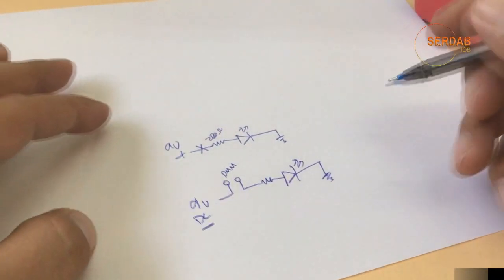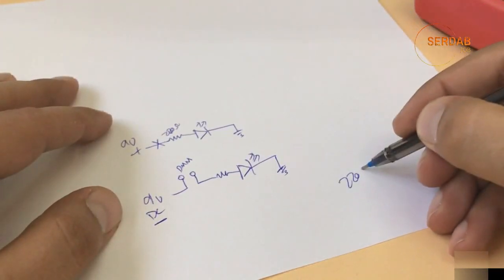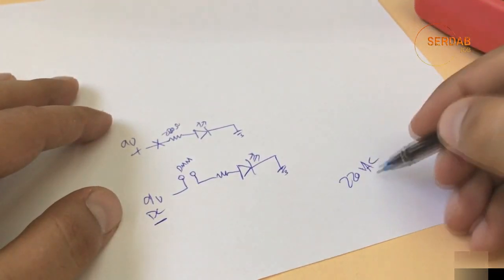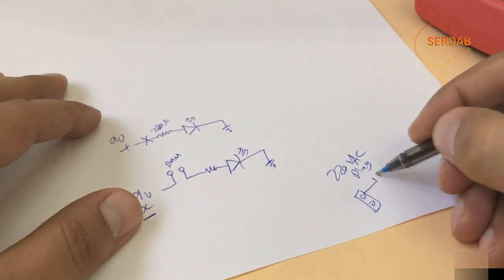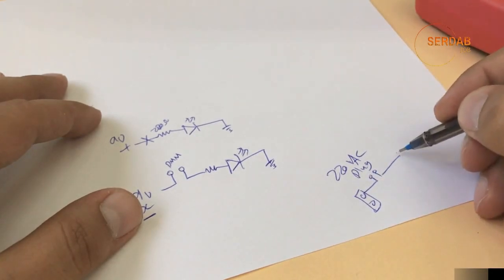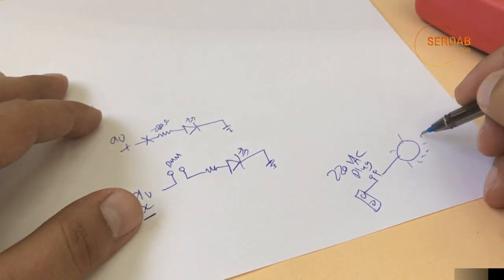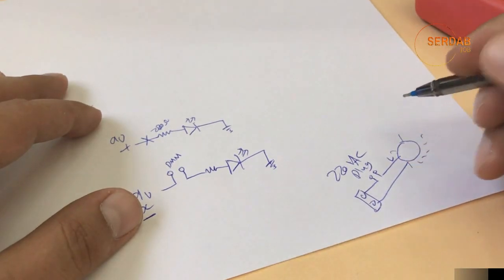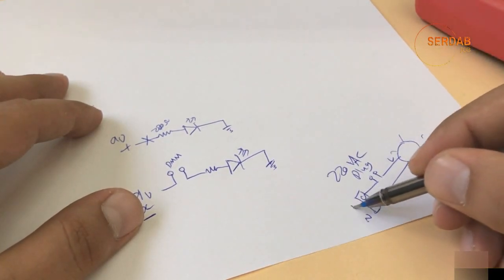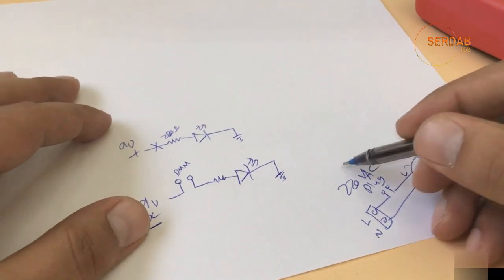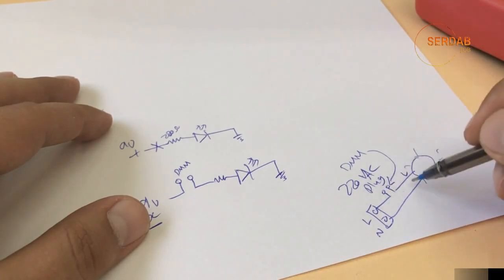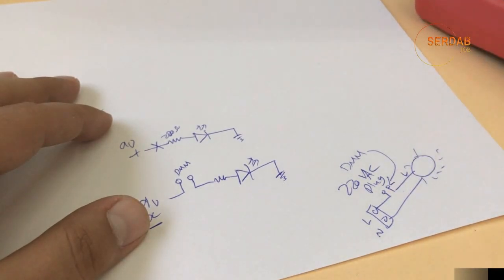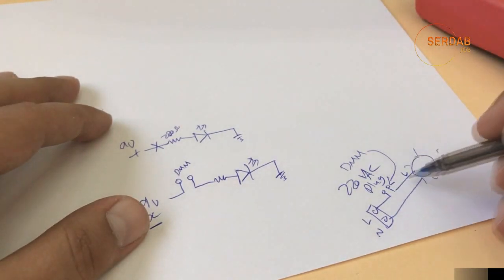If you want to measure a current that goes through, let's say, a 220 volt AC plug. Let's say that this is the AC plug. You need to go to the digital multimeter. Then let's say that this is a light bulb. This is the line and this is the neutral. The neutral will be connected directly while the line must go through the digital multimeter using these two probes in order to measure the amps that the lamp consumes.